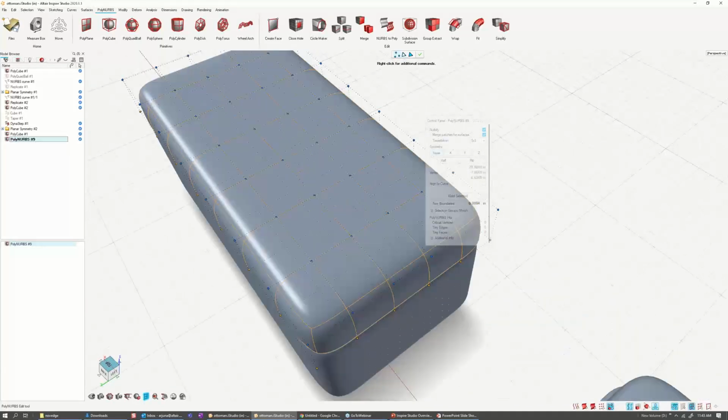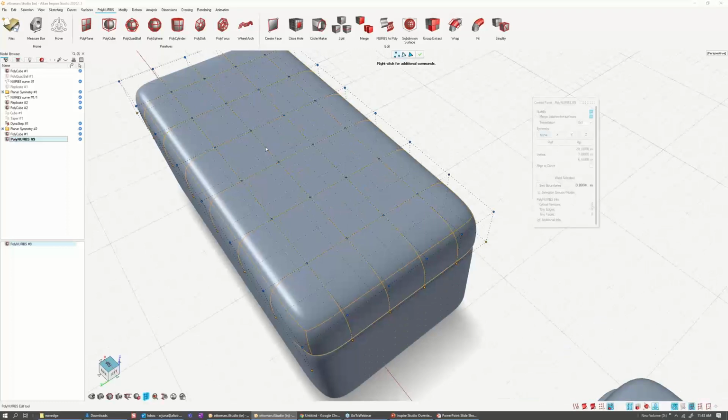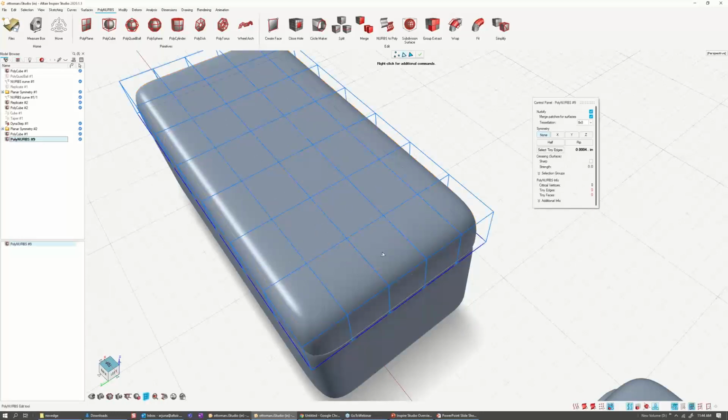So what I can do is select some of the vertices that I want to be part of that design. So I can say I want this. Right now you can see there are 4 in between. So we can delete one of these loops by selecting the loop and deleting it. The reason I'm deleting is because I want an uneven number here. I'm going to delete this.